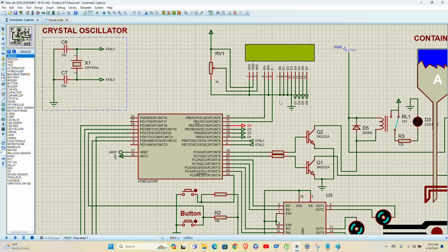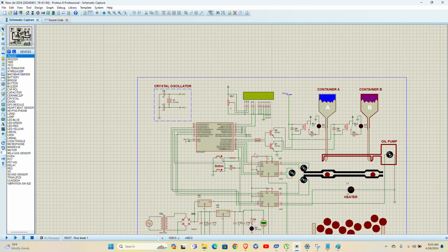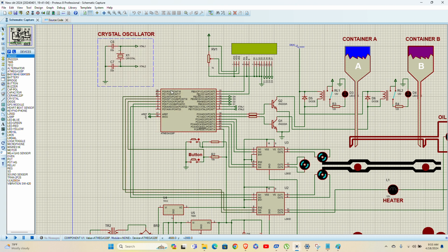As you can see here in our microcontroller, we only have 3 pins remaining. So if we had to use all these pins, it would be hard and difficult for us to display any character here, because we would have 1 pin remaining from the connection. So for example here 1, 2, 3. We would take 1, 2, 3, but 1 pin would remain. But the advantage of using 4 pins, which is the 4-bit configuration, is that we can use few pins to display this.